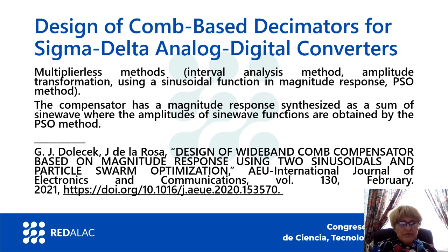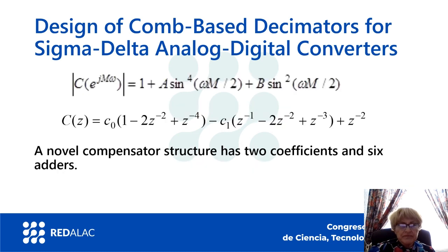In this presentation, I will present one design presented in this reference from 2021, where the compensator has a magnitude response synthesized as a sum of sine waves, where the amplitudes of the sine wave functions are obtained by the particle swarm optimization method.